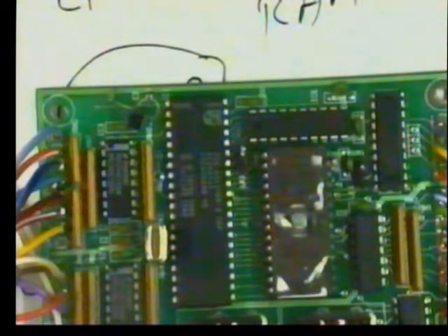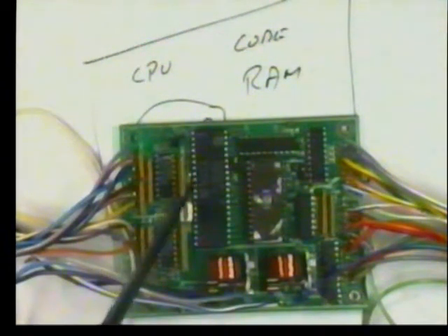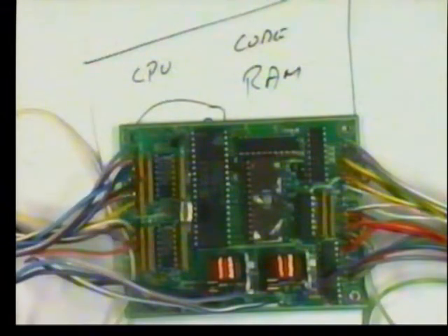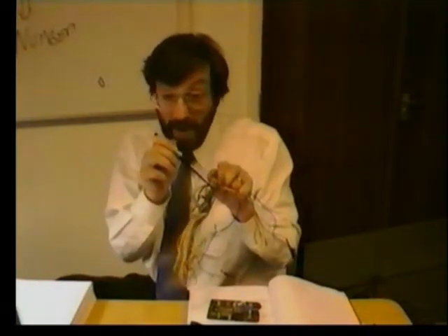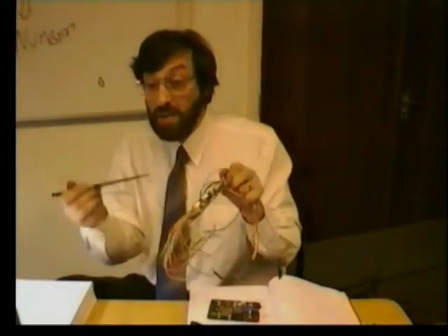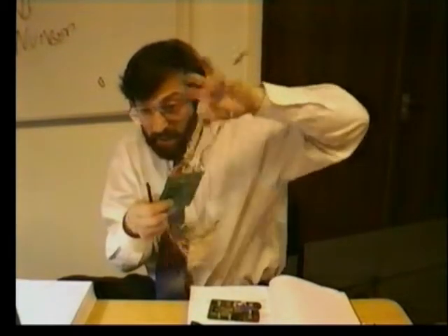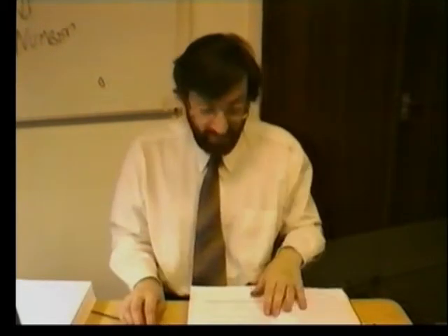Our program can input the state of these digital pins from the outside world simply by accessing these pins, which are memory mapped at fixed memory locations. So all we have to do, in a C program, is set up a pointer that points to that memory location, and then you can write a program that directly operates on an input signal from the outside world. Very simple to do.